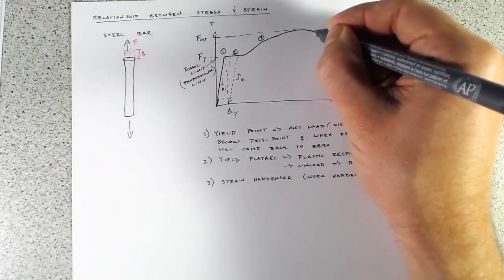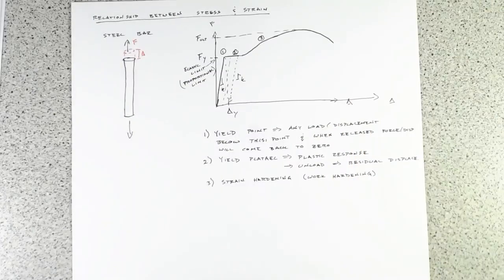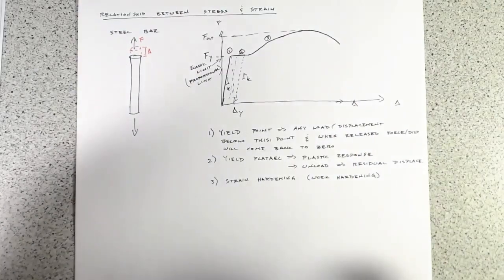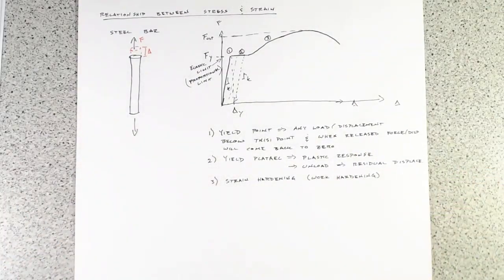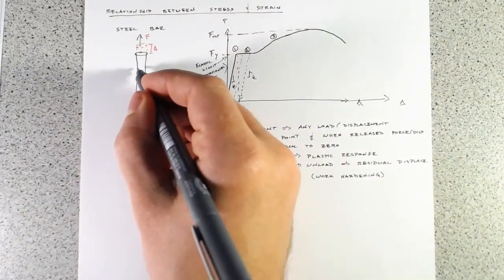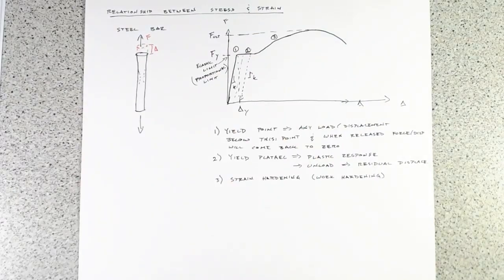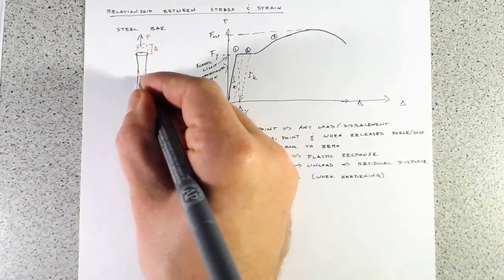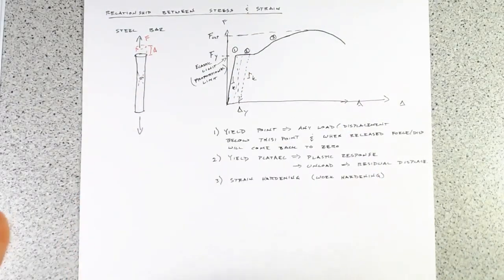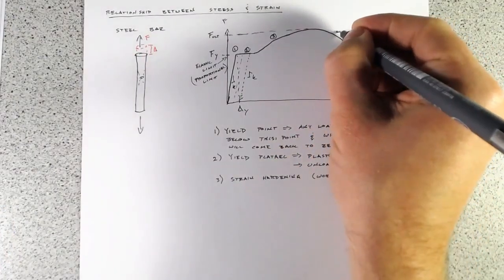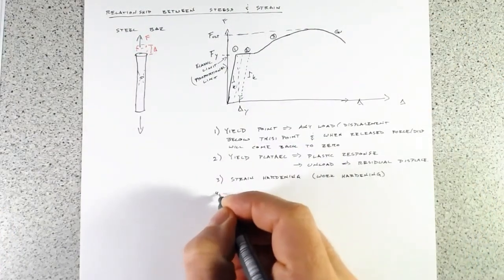But then we find that the material actually starts necking down, where if you pull it far enough, you see it gets thinner here in the middle. So as you pull it, it stretches out like if you've ever seen saltwater taffy. It's doing the same thing. And this region is our necking region.